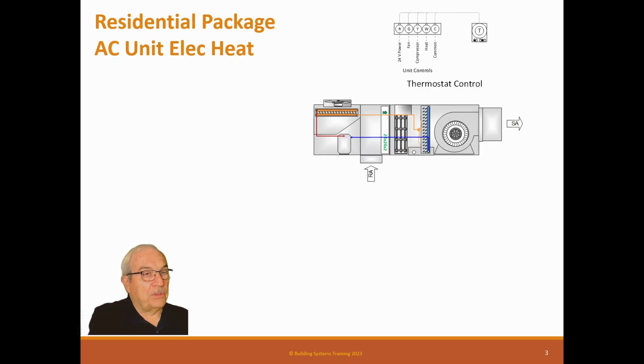The main difference between the two, now, by the way, these residential units, we use them on commercial all the time, is size. So if we need a 2-ton unit on a commercial job, it'll be a residential unit. They don't make a 2-ton commercial unit. And there's really no difference. The main difference is in cost. Because on these residential units from 1.5 to 5 ton, they make millions of those. In commercial units, they only make thousands of those. So the difference because of volume is cost. These residential units cost much less per ton than a commercial unit. So that's why we use a lot of them.